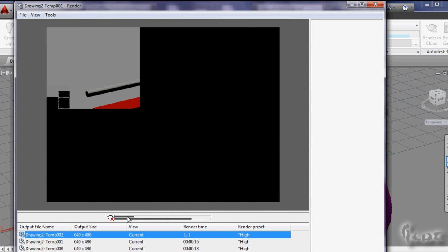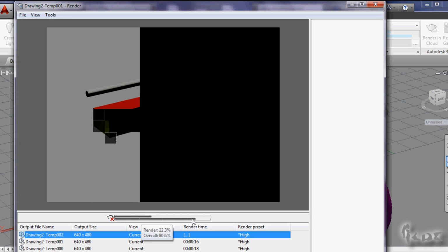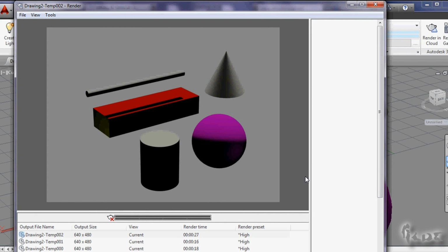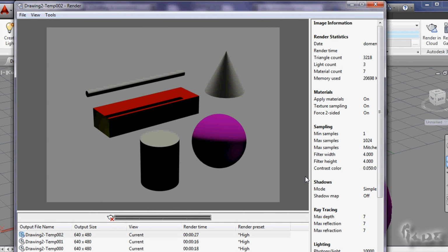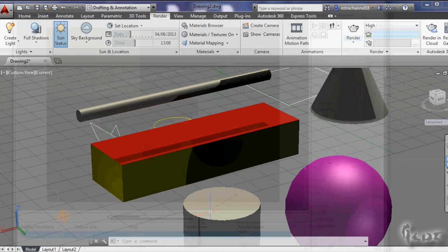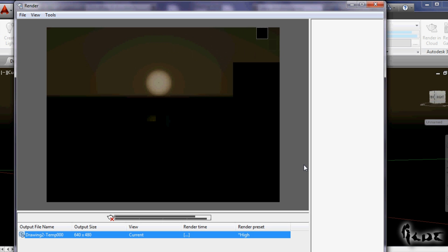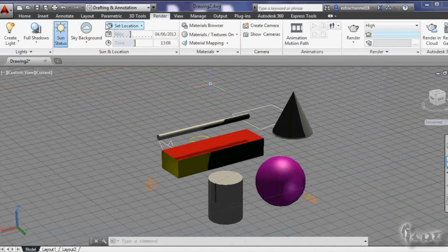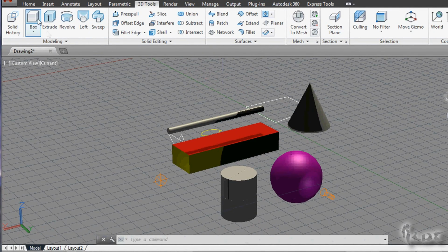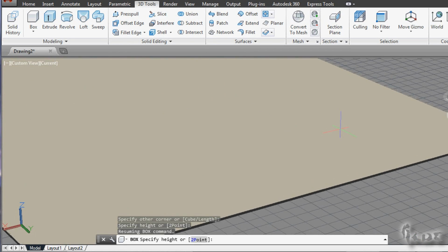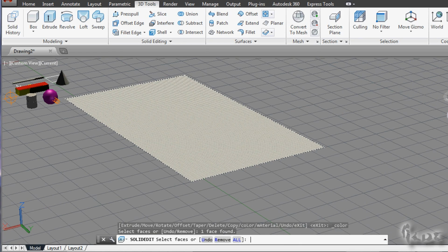On Render window, the white squares you see are the parts of your project that are being rendered by your processor. And you can check the render status through the bar right at the bottom. Remember that only the portion of your project that you see in your workspace is rendered when you press the render button. The render will report all illumination and filling settings. What is not reported is the horizon, which is made through a color change in the sky, if enabled. So, in case you want to create a grass ground, you actually need to build it on your own. In the easiest case, using a box with a very short height and colorizing its upper face in green.